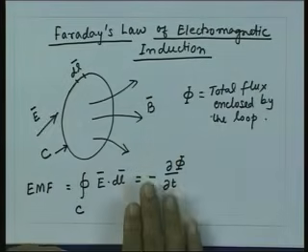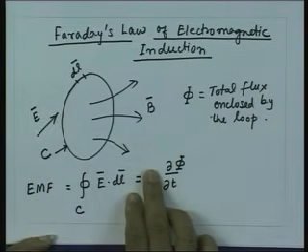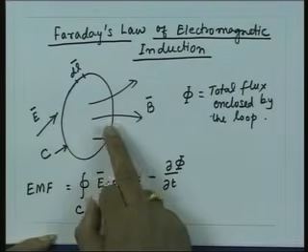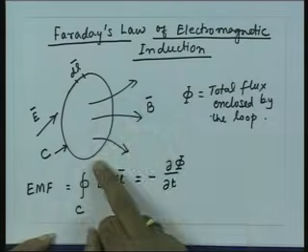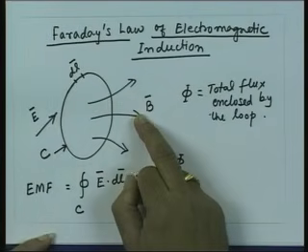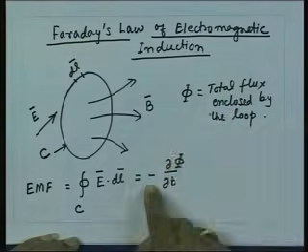Suppose the negative sign was not there, what that means is the magnetic fields will produce the EMF, which will produce a current, which will produce the magnetic field, which will add up with the original magnetic field. So, the magnetic field will increase. If the magnetic field increases, the EMF will increase. So, essentially there is no stabilizing element here, the thing will go on growing indefinitely. So, essentially this negative sign stabilizes.